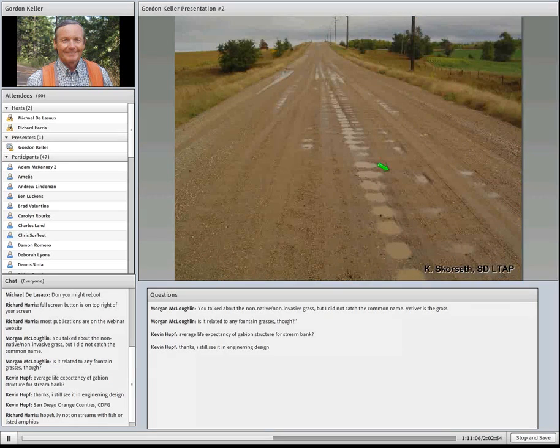But then maybe more commonly, there are problems like this. Just how well is it performing on the road? And it also comes back to how the road is shaped and drained. Are you going to be getting potholes, corrugations, or washboarding? Just how smooth is it, which affects how fast you can drive on it safely.